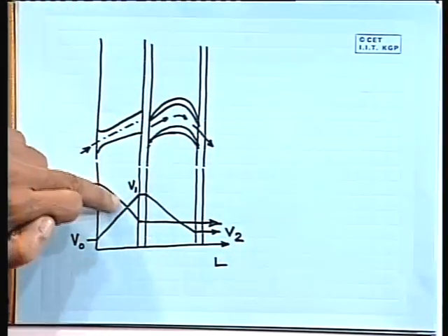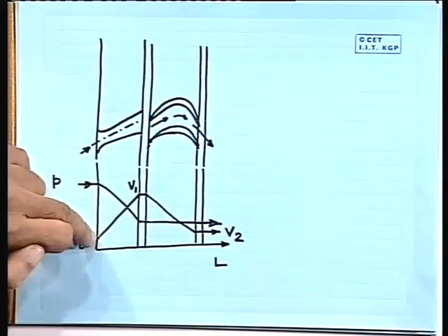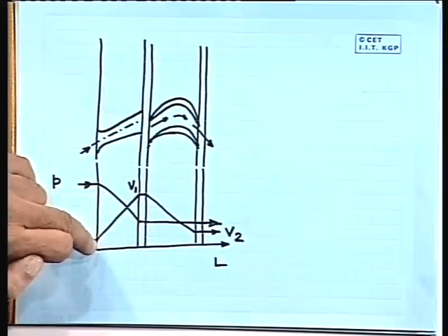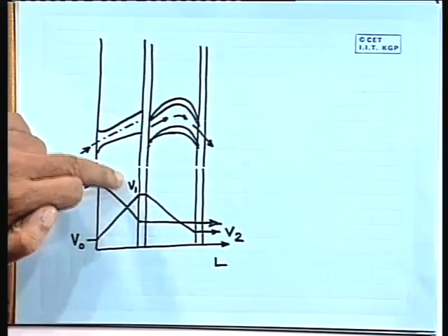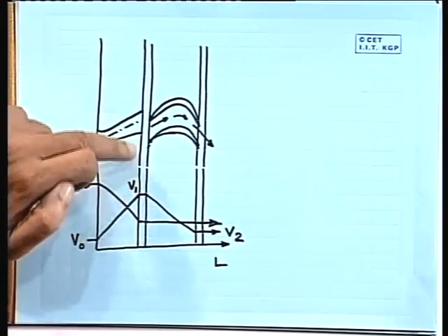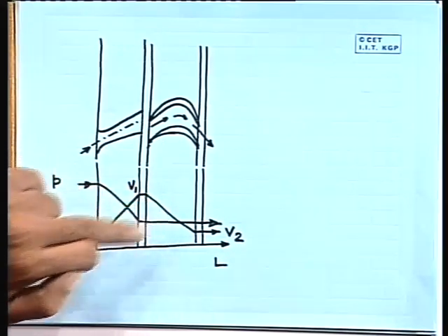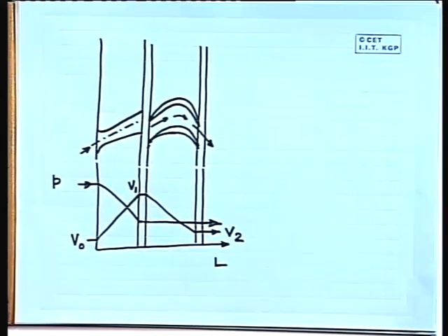In the nozzle there is a drop in pressure and velocity is increasing. And then when the steam is passing through the blade passage, there is a drop in velocity. So, basically there are a number of conversions, and how much will be the inlet velocity and outlet velocity depends on nozzle design and blade design.